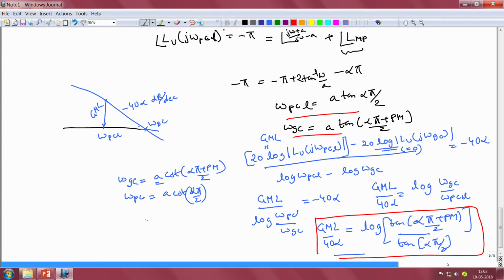So if we were to replace ωgc by A, which was the vertical y axis of the graph that we showed in the previous clip, which plotted the best achievable gain crossover frequency as a function of the gain margin for different phase margin values, if we were to replace that with the inverse of it, namely A by ωgc, then we can use the exact same graphs to predict what the minimum necessary gain crossover frequency is for the case of the unstable system.